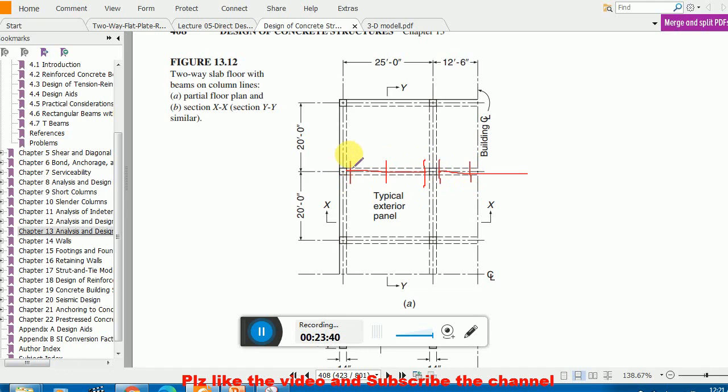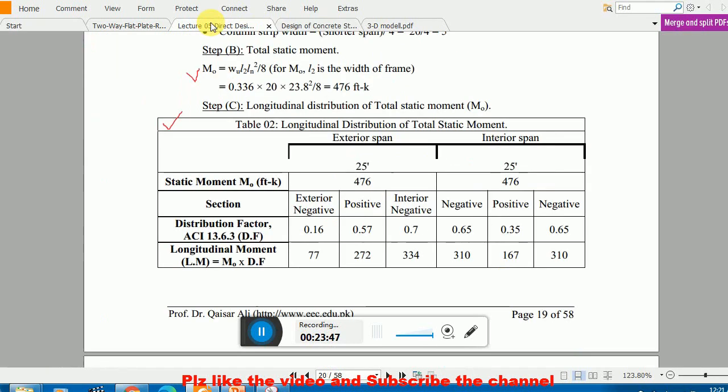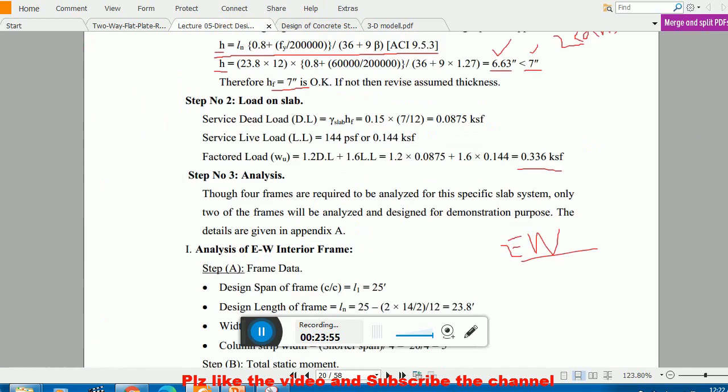In case of a flat slab system, you already know this is 0.26, this is 0.52, and this is 0.75, but here, as we have beams, these coefficients will change. I already explained these coefficients for a beam slab system.